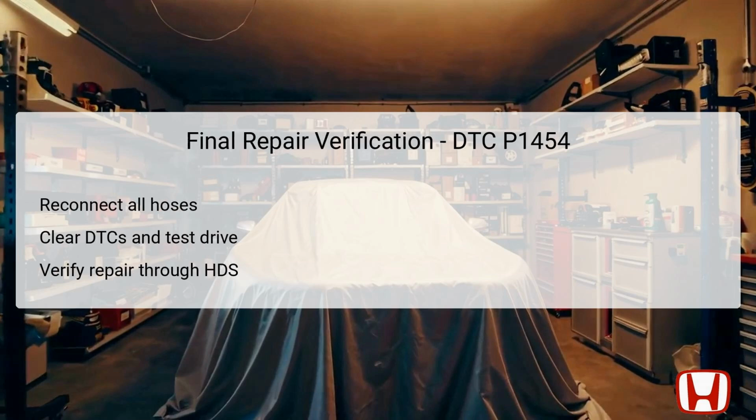After completing all the troubleshooting and necessary repairs, it's vital to perform a final verification to confirm that the issue has been rectified and that the vehicle is functioning as expected. Begin by reconnecting all the hoses and electrical connectors that were disturbed during previous inspections. After everything is reassembled, clear any existing diagnostic trouble codes via the HDS.